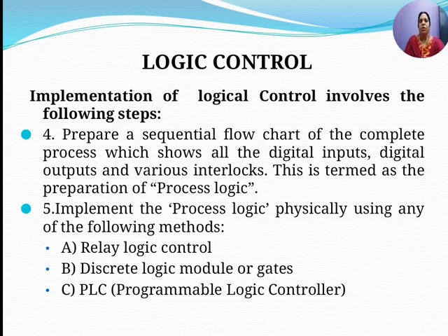After you identify the list of inputs and outputs, you need to prepare a sequential flow chart of the complete process, which shows all the digital inputs, all the digital outputs and various interlocks. This is termed as preparation of process logic.